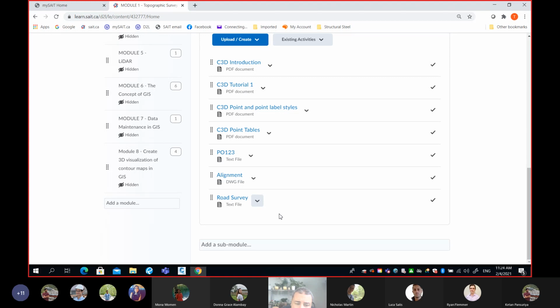Or if you're looking at, let's say, a tripod, you'll put 1.3 meters, or looking at the second floor, it could be 3 meters. So you add the target height, and then finally you place your target point. Remember, you're checking the visibility between 2 points. So the 2 points should be known, and also the target height and the eye height should be known.